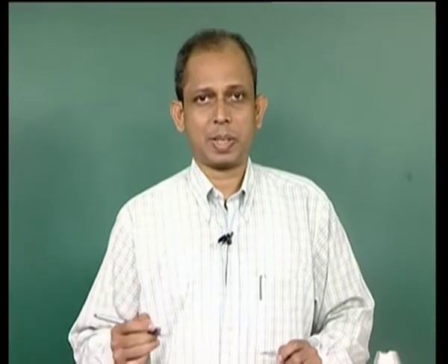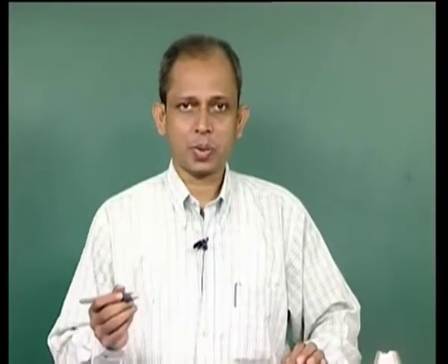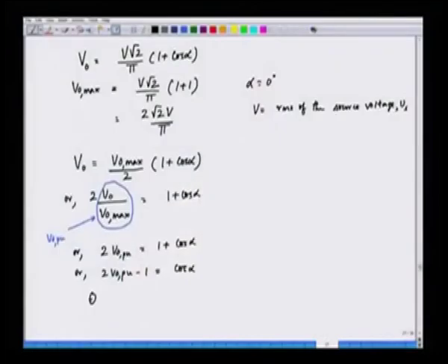Now, what is the reactive power here? The reactive power is Q, and Q is equal to voltage into current into sine of the angle between them. So, we can evaluate Q as follows. Q is equal to, what is the voltage here? V RMS is V. So, we have the V here into, what about the input current?